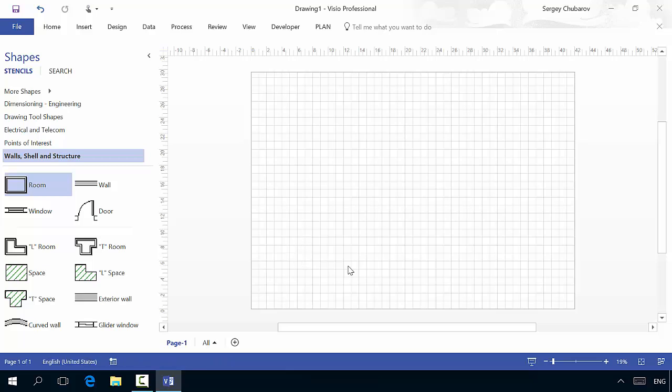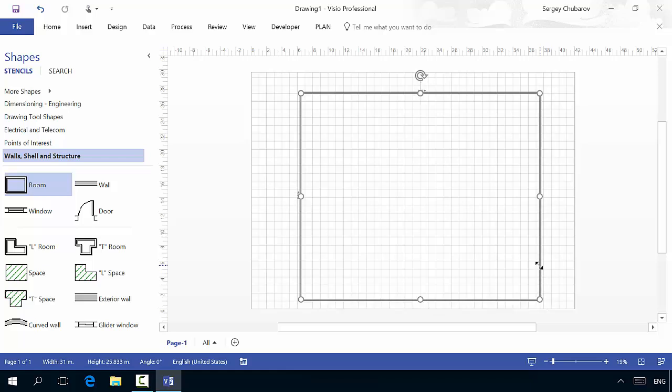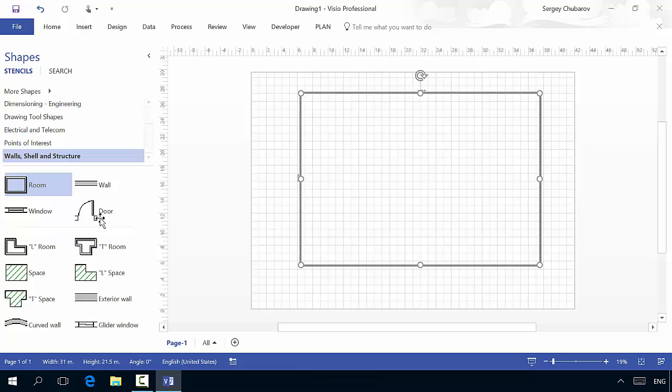So let's work. We're gonna create a shell, and it's gonna be our first element. I'm gonna set a size and start to add some walls. So let me add some walls. First wall, I drag it to my shell. Here we go. I need to glue it to geometry, and I'm gonna set a size.